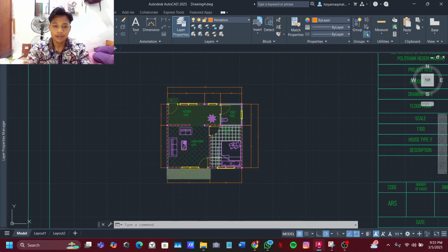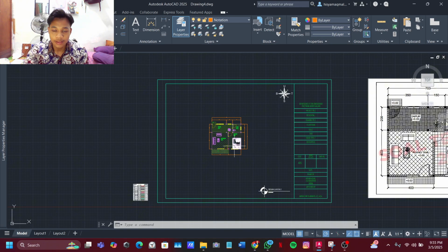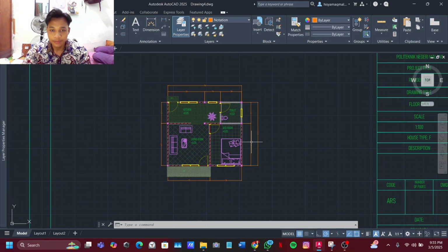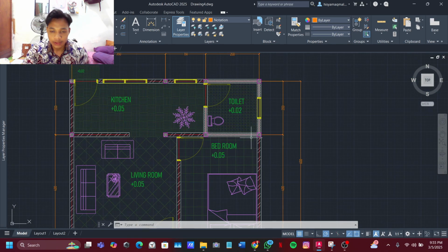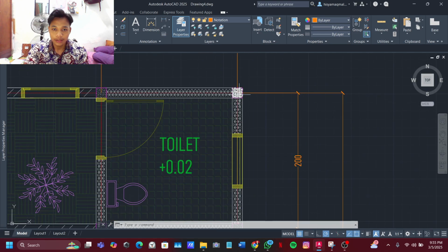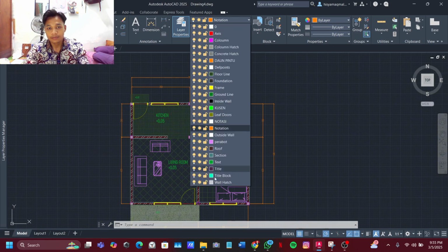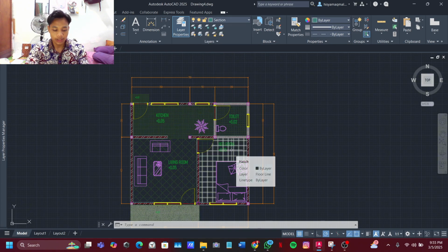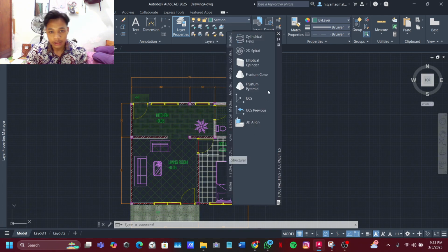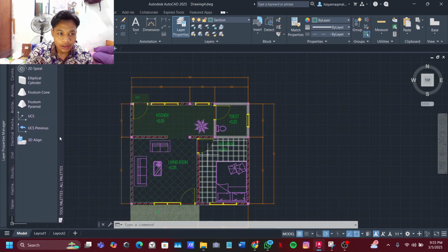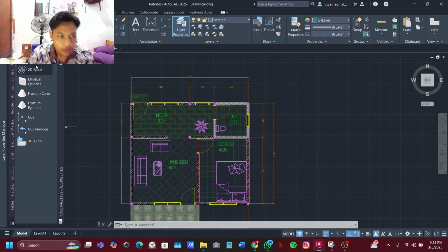Okay, I forgot something before we finish this drawing. We have to put the annotation for giving the place of the beam, like the columns and the sectional. For that, we're taking the section layer and just the control tree, so it will give the properties of this.